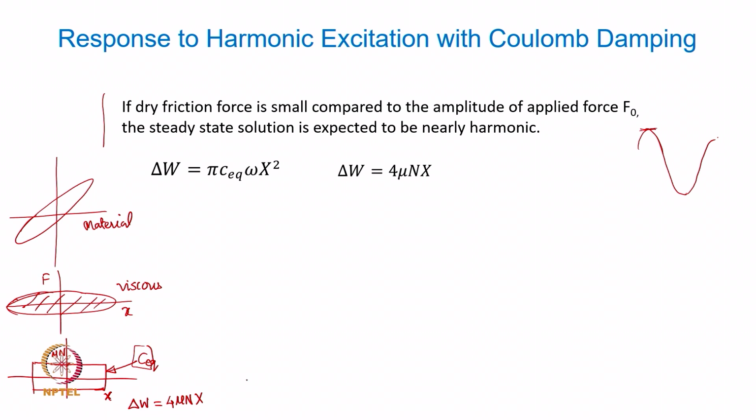We are not interested in finding out whether the response is, let us say, 1.32957 like this. Even if we get the response to be this much is good enough for us, slight variation is okay. So, for all practical purposes, getting an equivalent damping by equating the energy dissipated in a cycle irrespective of what is the underlying mechanism should suffice in getting an approximate response value.